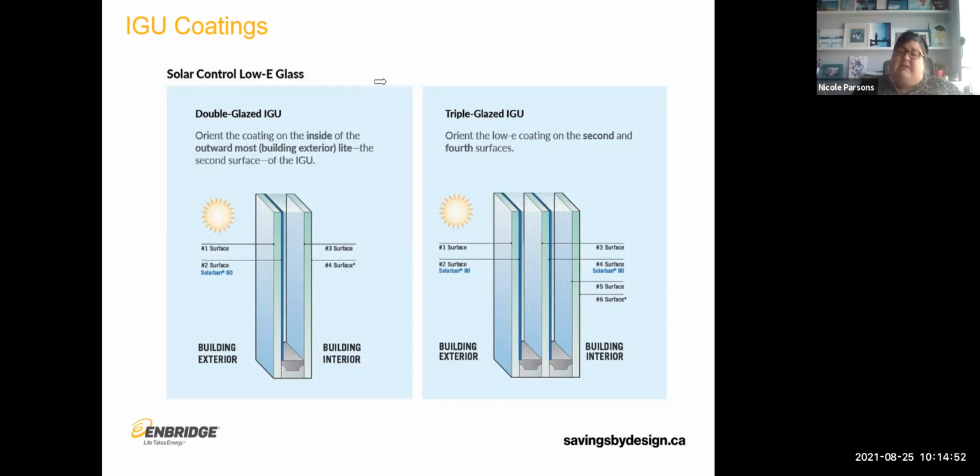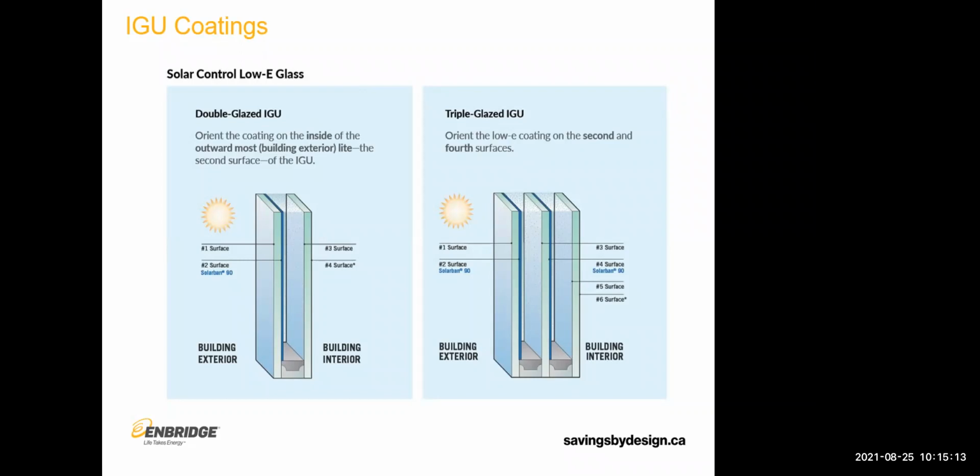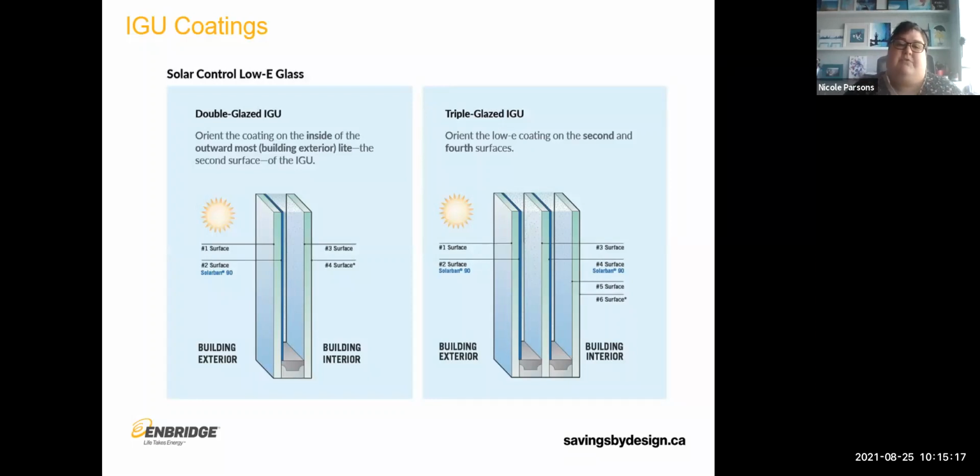So that's definitely, I don't want to say a shortfall, but that's definitely a potential weak point when you're talking about modeling assumptions versus actual performance. So really the way to do that is to verify that. And the assumptions are made based on testing of existing buildings, right? A lot of the air tightness that's used in modeling is based on what built buildings do. So verifying that the building has actually been built to that standard is really the important part.